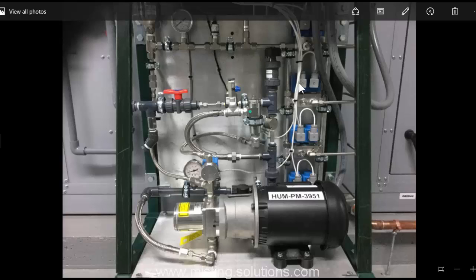So what we do is when that zone 1 shuts off and the pump quits running, we open up zone 4 for 3 seconds like it is running, but it's not. Dump this high pressure water into zone 4 for 3 seconds, open it up, and then close it again, and any high pressure water that's accumulated in zone 4 then does its dump valve to drain. So this line has been reduced from pressure, and so has the dump valve on zone 4. Little complicated, a little hairy, but it does work quite well. So you'd have to think through it, listen to that a few times to understand what's actually going on.